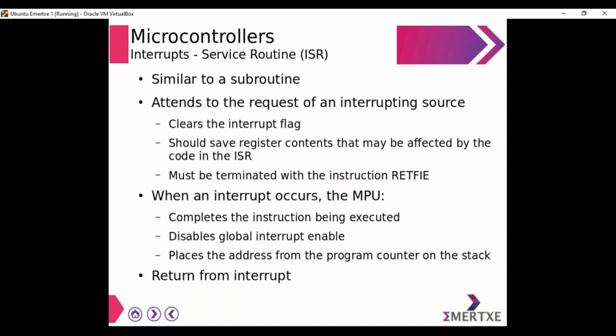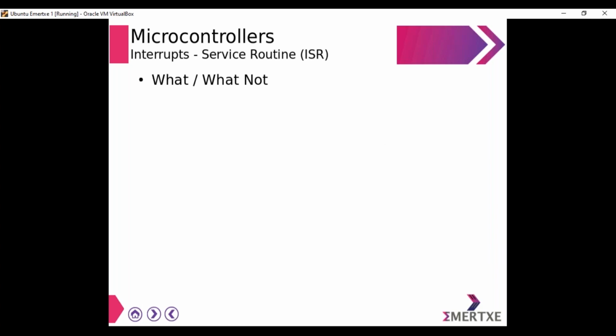So RETFIE is an instruction which will bring the control back from an ISR to execute the rest of the instructions. That is return from interrupt. So this is what happens whenever an interrupt occurs. I hope you are able to follow.